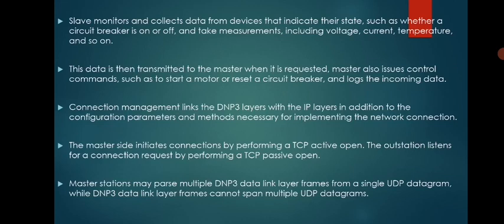So here the DNP3, as I said, totally depends on the SCADA principle, and the IP layers work based on the internet protocol fashion. They are on one side each. So in the intermediate, we need to go for some configuration or connection management links, which are responsible for converting the data fashion of DNP3 to IPv4 or IP version packets exactly.